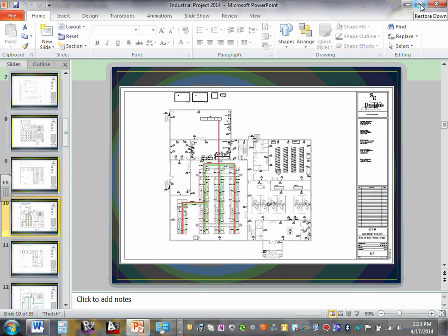So a 25,000 square foot, two-story building: manufacturing floor, support area, data center, with an office area. And we're supposed to size the power. We're focusing on the power here. We need to size the lighting panels, as well as the receptacle panel or panels, mechanical equipment panels, as well as, of course, the main feeder and the bus ducts, using the NEC code book and the loads that we have been given by our mechanical counterparts and process engineers.